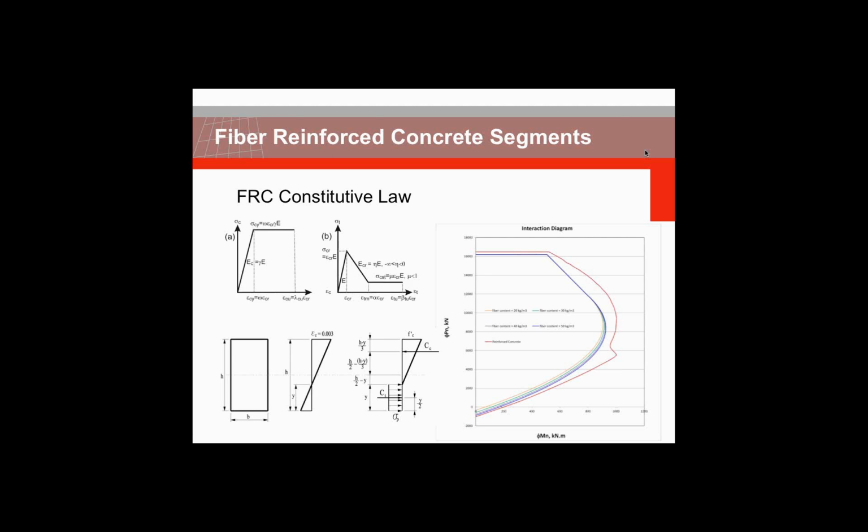Using this constitutive law, a parametric study is shown on the right-hand side. You can see the effect of fiber dosage increasing from 20 to 50, and by that the axial force and especially bending moment capacity is increasing and getting close to reinforced concrete.